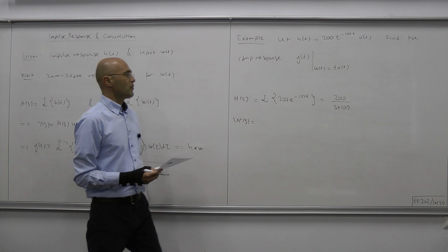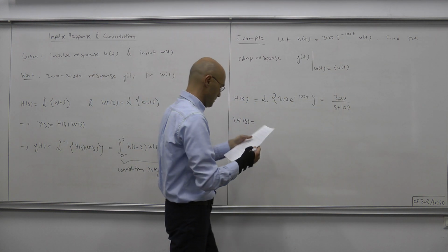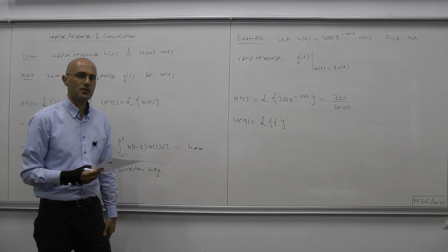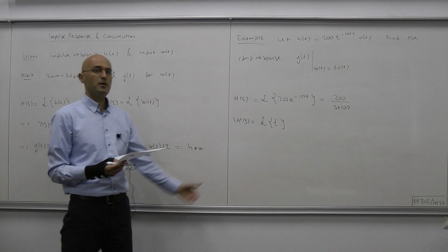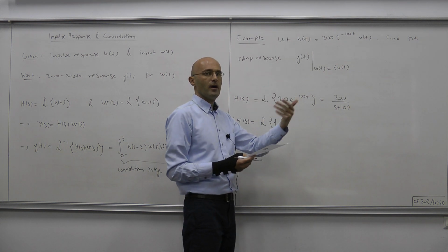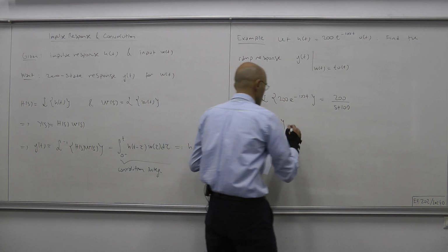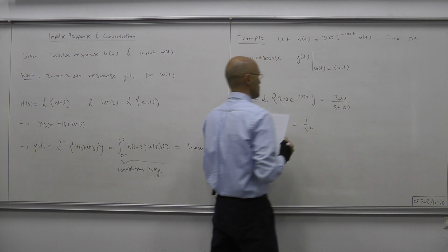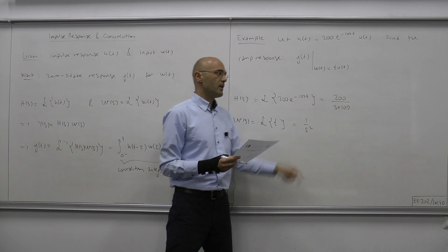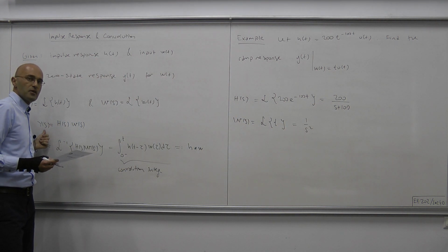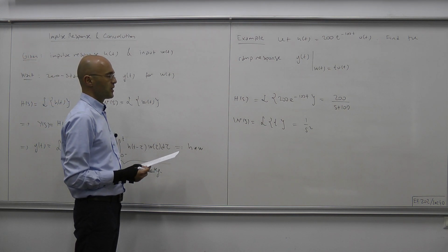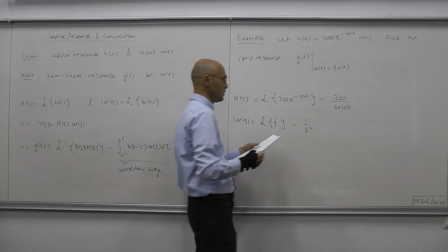And what's the Laplace transform of the unit ramp? It's the Laplace transform of t, which is the integral of the unit step. And when you integrate, you divide by s in s domain. So 1 over s divided by s produces 1 over s squared. Okay, h of s is here, w of s is here, therefore their product gives us y of s. And then by inverse Laplace transforming that expression, we can obtain y of t.